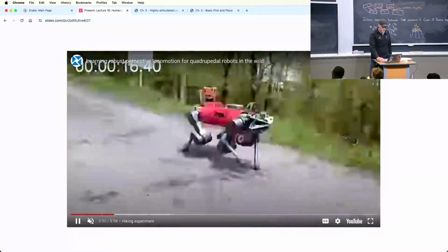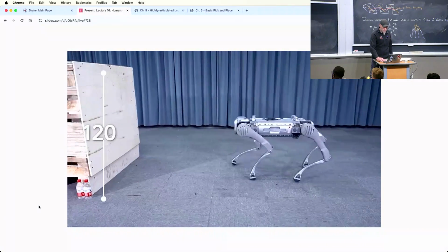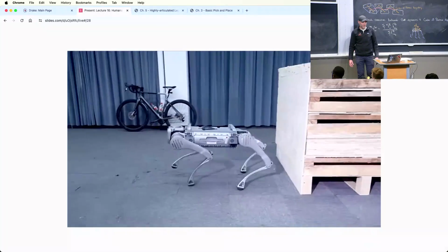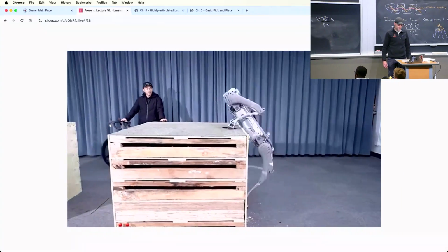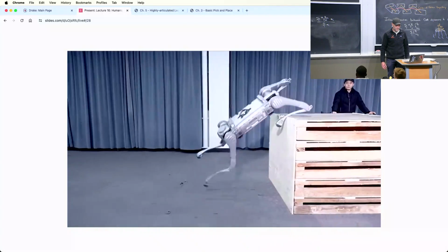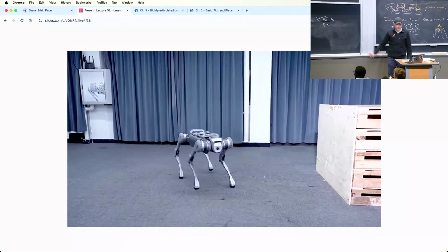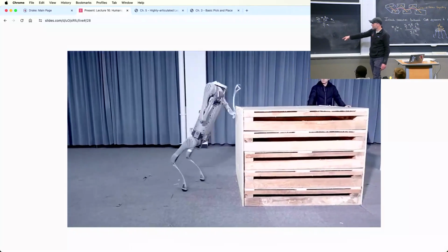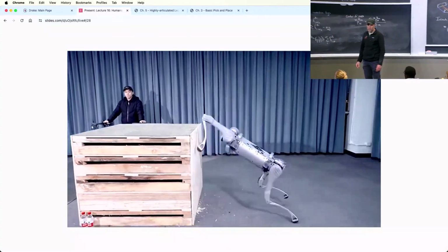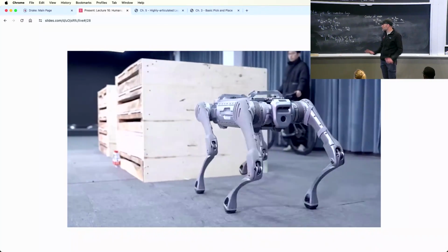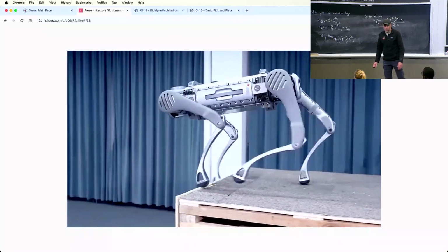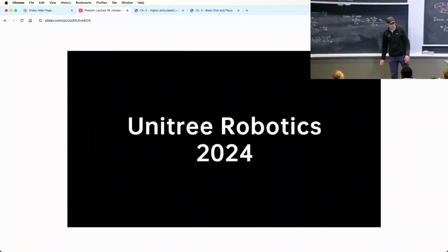And nowadays, we're seeing more and more just awesome results. That is still one of the coolest things I've seen. This is Unitree a few weeks ago, yeah. That would have been hard to plan with these techniques because torque limits, for instance, matter. All the limits of the robot matter. So the abstraction of being able to place your foot independently of the location of your body just doesn't work anymore when you're right at the dynamic limits of the robot.